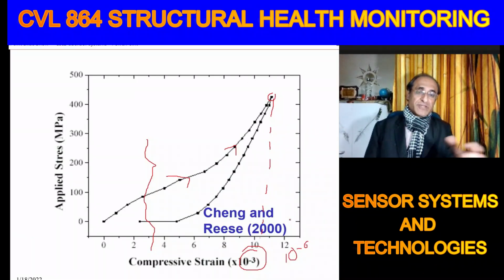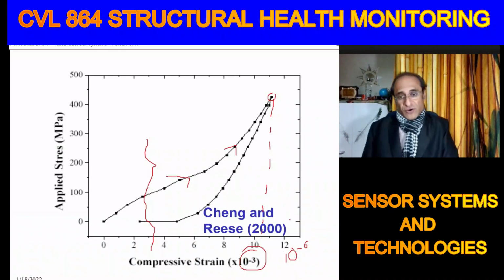Of course in tension, like concrete is weaker in tension, in the same way piezo materials are also weaker in tension. They undergo less strain, with lower ultimate strength in tension as compared to compression. But compared to concrete, if we are embedding these sensors in concrete, we are sure that they will not prematurely fail. They will undergo large stresses, and they have very high fatigue strengths also.